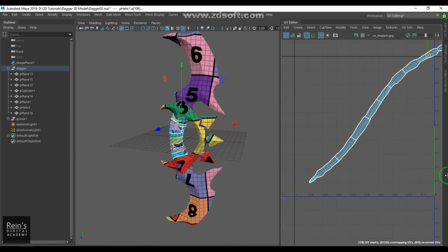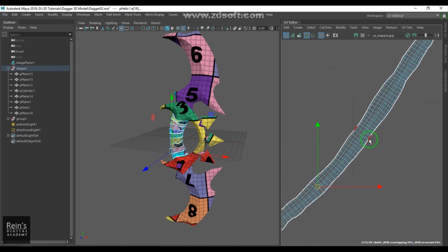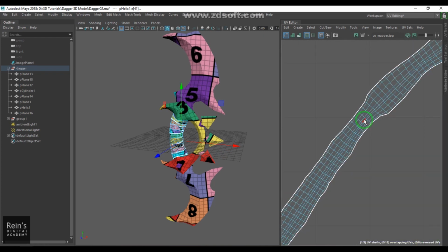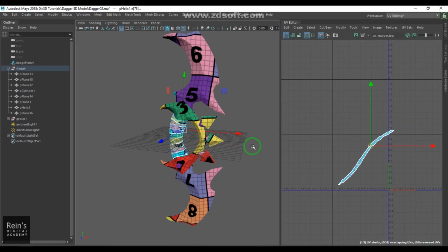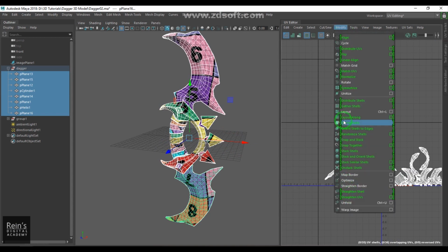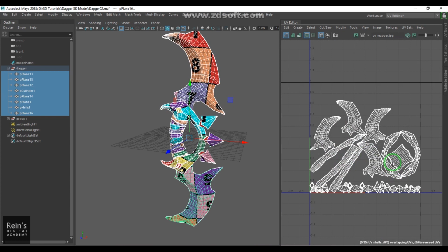Let's say if the cuttings are too small, then at least you can think of a little bit bigger one, I mean, avoiding too many seams, bringing up fewer seams. Okay, so I've cut this object. Then again I'll apply layout, and you should be able to see things are much better this time because I've cut them.